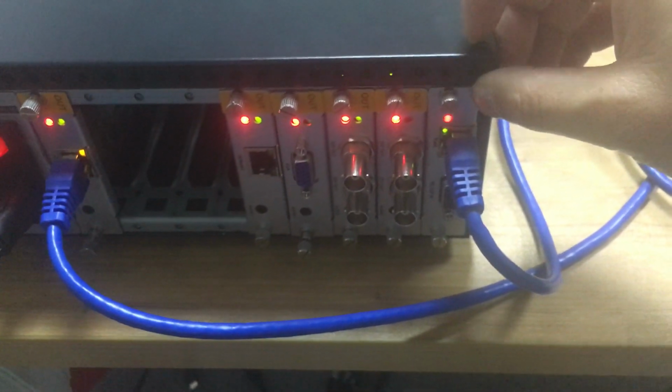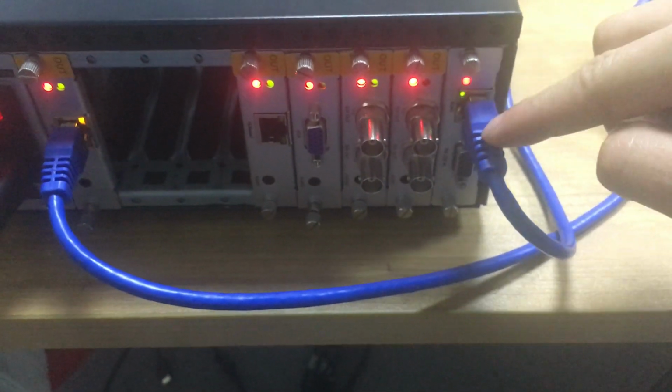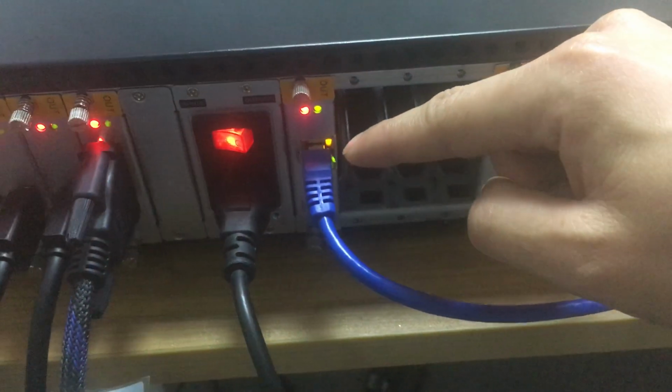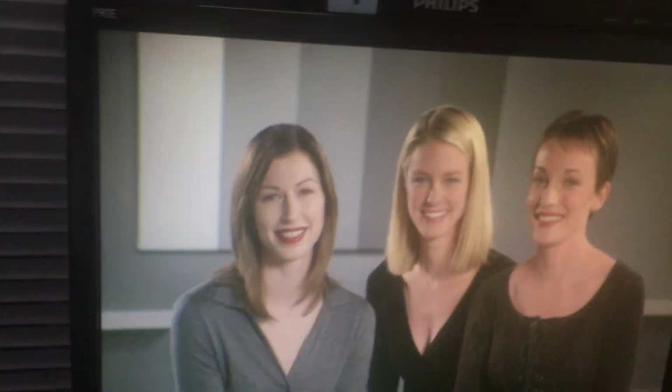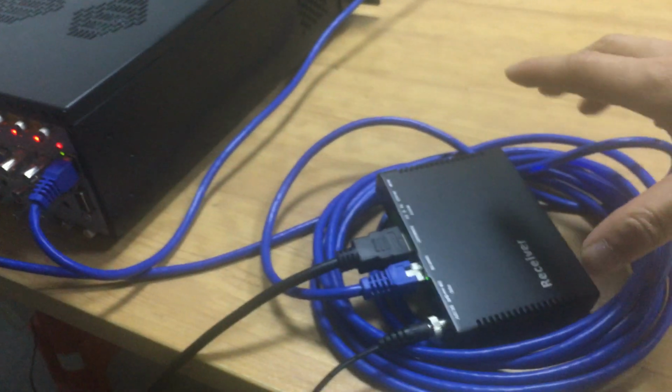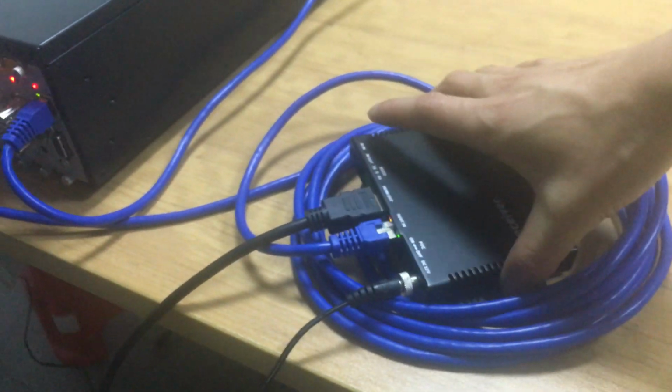And this one is for the control. For the control we can use the line control, or we can use the RS232. For these 2 HDMI outputs, we'll just screw these 2 TVs on top. It's actually a 1x2 video wall. For the DVI, we go to TV 3 here. And for the HDBaseT, we have the Cat6 cable going to this receiver here. Then we get the HDMI output to this TV here.